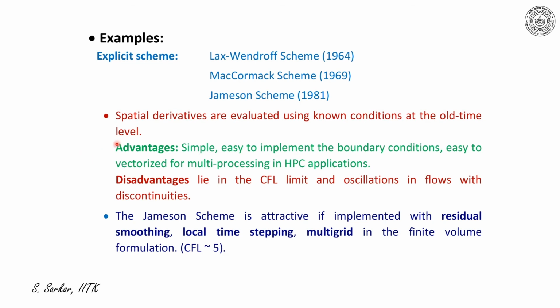Advantages are they are simple, easy to implement the boundary condition, and easy to vectorize for multiprocessing application in HPC. Disadvantages are the CFL restriction, that is, the time limit with which these schemes will be integrated is severely restricted, and thereby a large number of time iterations will be needed for a steady state solution.